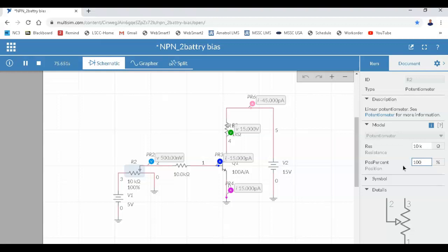So according to this, how much voltage do you have across the transistor? Usually when a transistor saturates, it's always going to drop some voltage, right? Because there's always something in between there. Here it's showing it's dropping nothing. Are we okay? Yes or no?